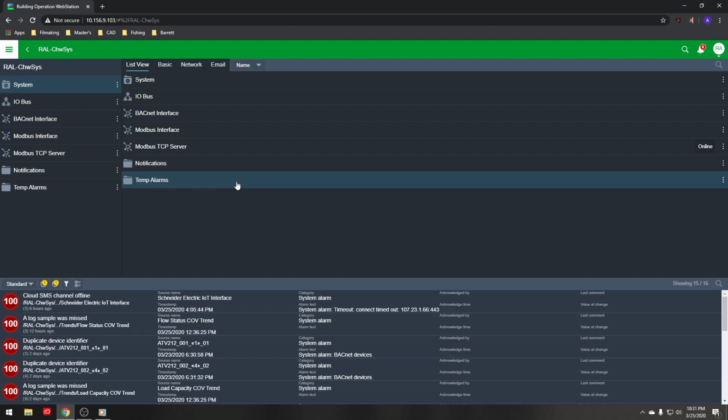the chiller plant. So, as we talked about briefly, the difference between monitoring and control software. This is the software that actually controls the chiller plant, the pump speeds, bypass valves, what the chillers should do, how they stage, given certain failures, how they share load, things of that sort. And we call that a sequence of operations. How does it operate?